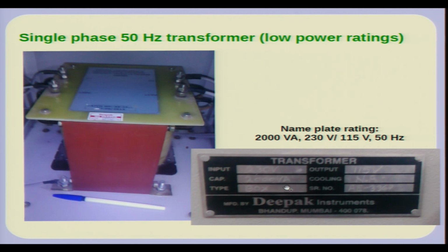Now, one more interesting point you would notice is that it also has a voltage rating. So, the voltage rating has two reasons. One is, of course, if you apply very high voltages, remember that these coils of wires are insulated from one another, and if the voltage is very high, the insulation may fail. The electrical field is caused because of the high voltage. Remember that I had mentioned this earlier, that between the coils of the wire there is this insulation material and there is an electrical field.